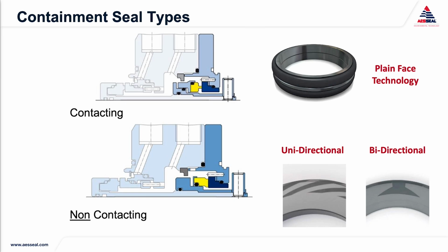However, in normal operation and under primary seal face failure conditions, the leakage will be commensurately higher than in contacting designs. The grooves in the face can also clog with primary seal leakage and debris, especially on Plan 75 applications, if not supported correctly with a Plan 72.